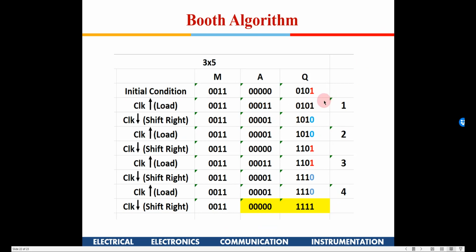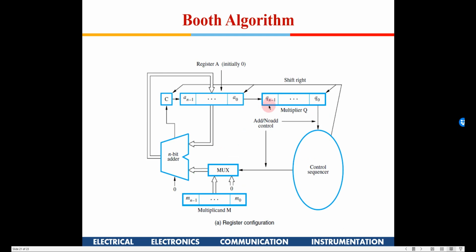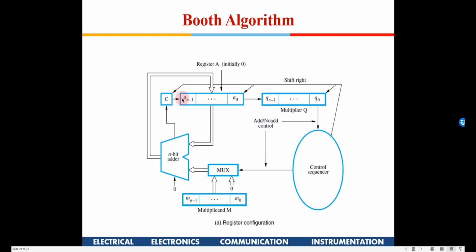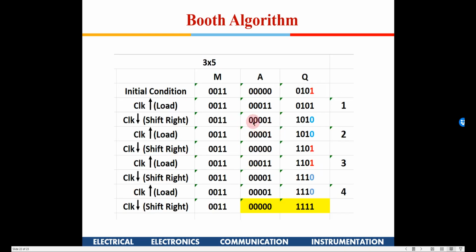So this 1 gets thrown away. So this 0 comes here, 1 here, 0. This 1 from here comes here, because they are in series. From here to here it is fed. So this 1 comes here, 1 here, and then 0 is pushed in from here. Okay, always 0 will be pushed in. So a 0 is pushed here.